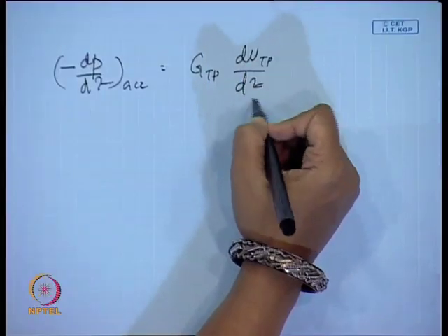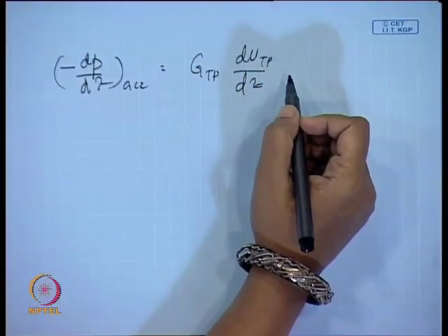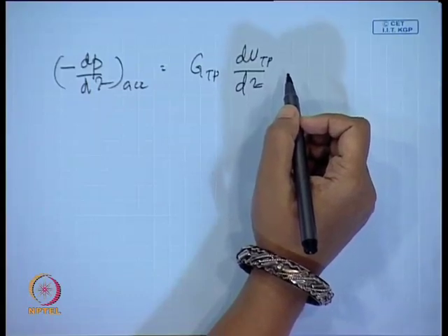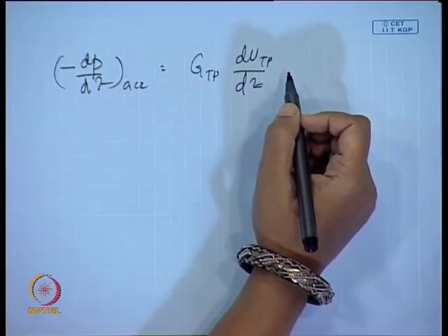But there will be an acceleration pressure gradient whenever there is a two phase flow, particularly when one of the phases is a gaseous phase. We do not say this for single phase liquid flow. Agreed? So this acceleration pressure gradient arises just because one of the phases is compressible, in other words, considering compressibility of the phases.